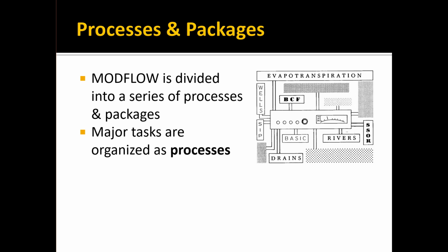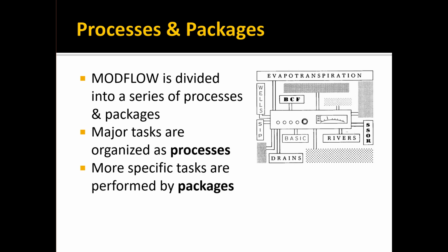But primarily we use the flow process, and within each process, more specific tasks are performed by what are called packages. So a package simulates a very specific feature or element of your groundwater flow system or of the solution.